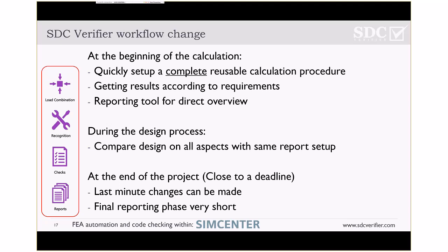If you work with SDC Verifier, that also has a positive change in your workflow. Because at the beginning of the calculation, you can quickly set up a full calculation procedure. You check on yield, you check on plate buckling, you check on weld strength. You do all the checks at once, instead of what you normally do: let's first do a check on yield, and when that's okay, then we go to plate buckling, and then we go to welding.